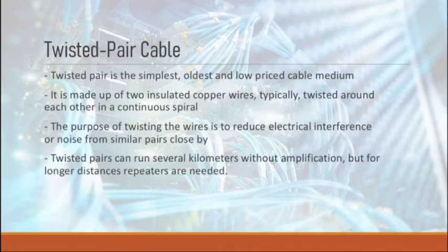The most basic form of twisted pair wiring consists of one or more pairs of insulated strands of copper wire twisted around one another. These twists are important because they cause the magnetic fields that form around a conducting wire to wrap around one another and improve twisted pairs' resistance to interference, while also limiting the influence of signals traveling on one wire over another, called crosstalk.